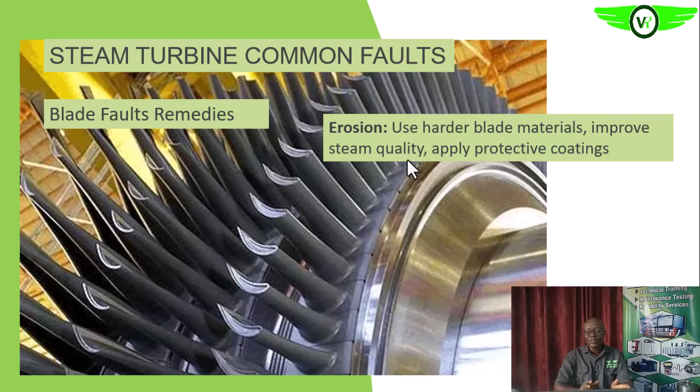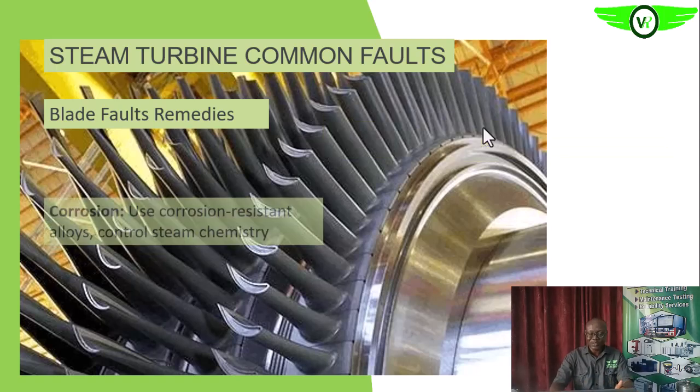Then two, we can apply protective coating, which is almost similar to the first solution, using the appropriate materials. Okay, applying protective coating that will be able to withstand or prevent erosion of the blade. So those are some of the remedies that we can adopt.